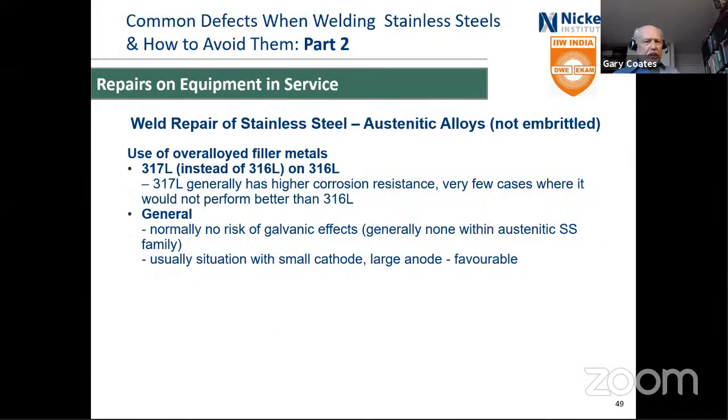You can use 317L on top of 316L. That's generally perfectly acceptable. There are very, very few cases where it would not perform better than 316L.